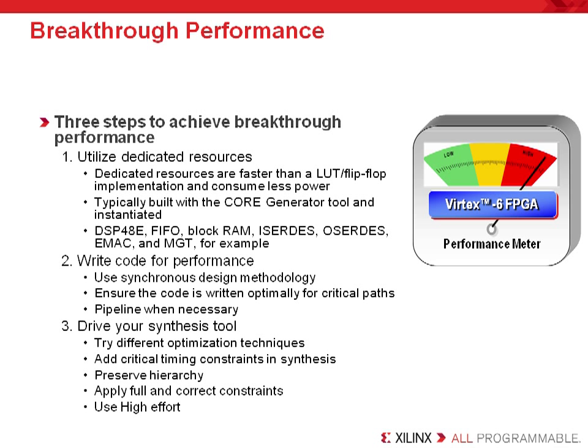Another very common FPGA design practice is for a designer to pipeline a timing-critical path. Now, this is done by inferring extra registers on a long data path so a long net delay or multiple LUTs in series can be tolerated. If you are not familiar with pipelining, don't worry, we'll talk a bit more about this later on.